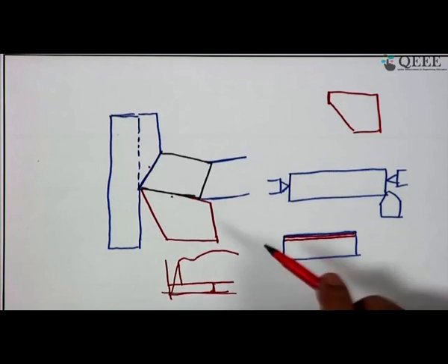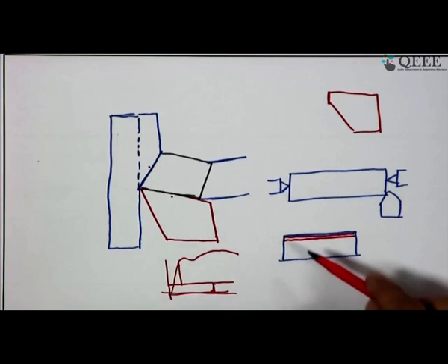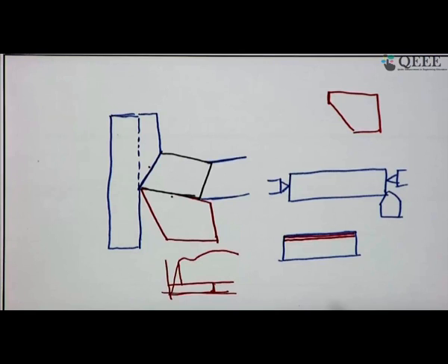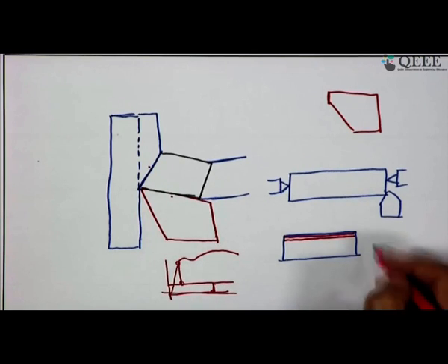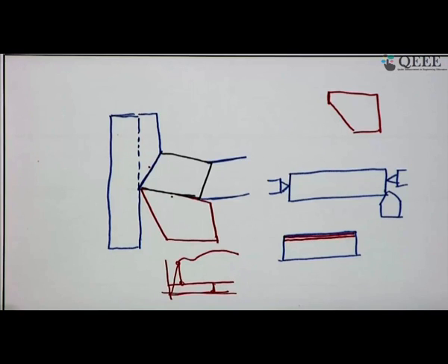When the material spins at a high speed, with an alternating stress, you can imagine that on the outer layer in each cycle it will be under tension, and that may lead to a fatigue failure, and the endurance limit will be less. So, obviously your life cycle will be less. So, these are the few things.